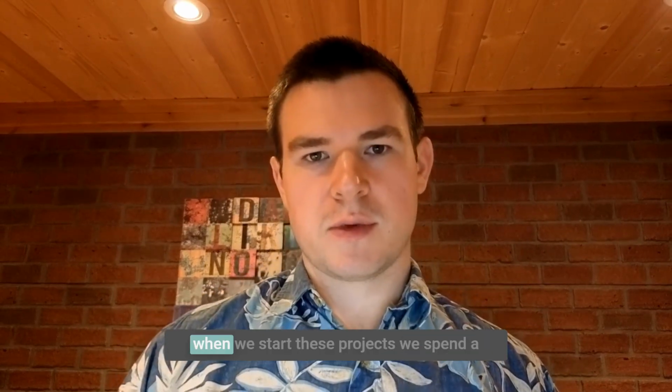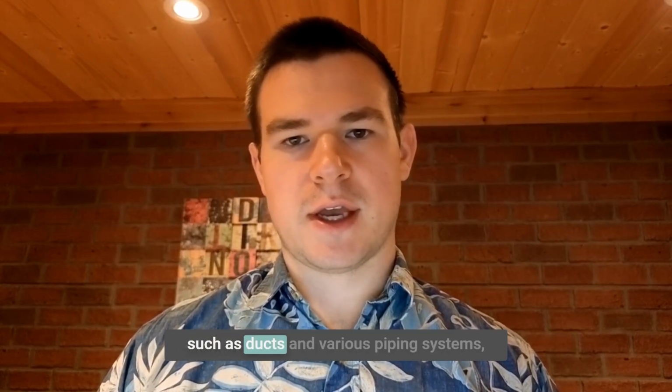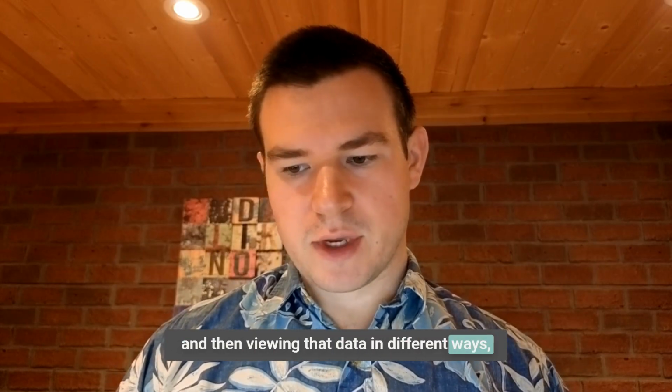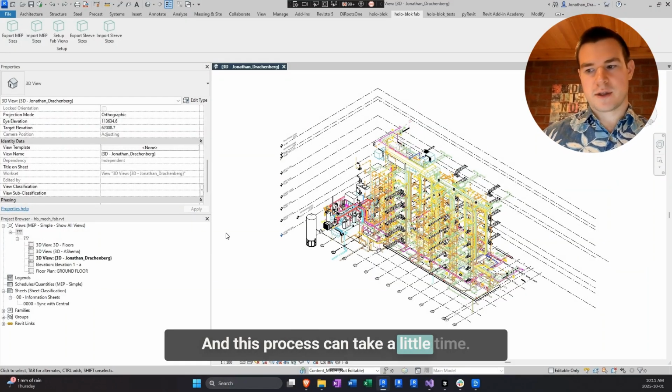We're starting a new mechanical fabrication project, and usually when we start these projects, we spend a bunch of time setting up lots of different 3D views that isolate different model categories such as ducts and various piping systems, and then viewing that data in different ways, both with links and without, and doing that for whatever different levels are in the project. And this process can take a little time.